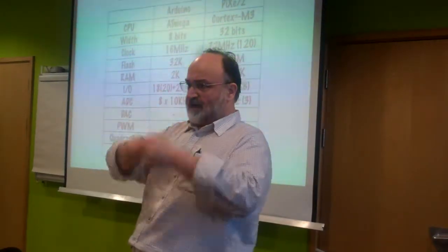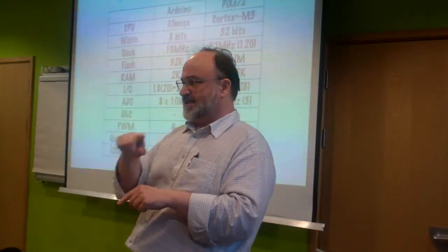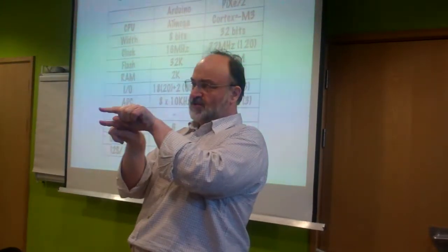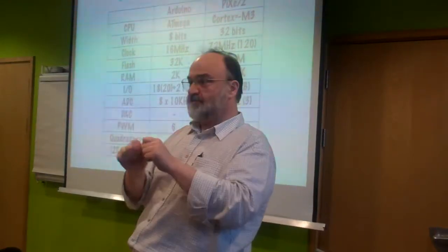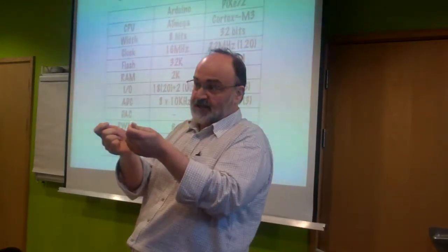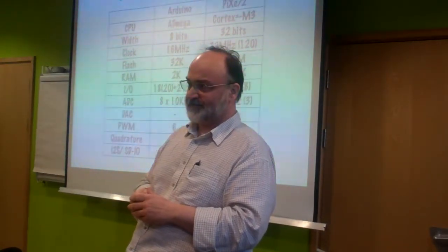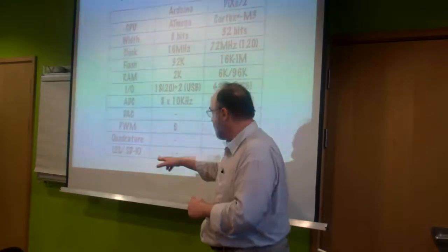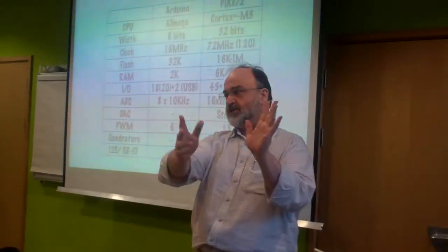It's 2 square waves that just get wiggled. If you just imagine you've got stripes on a disc going past a couple of sensors, by measuring the time that the stripe takes to go past the sensor, you can measure velocity. And by just counting them, you can estimate distance. There's hardware inside this chip in order to keep track of that for you. So you can unburden all of that.